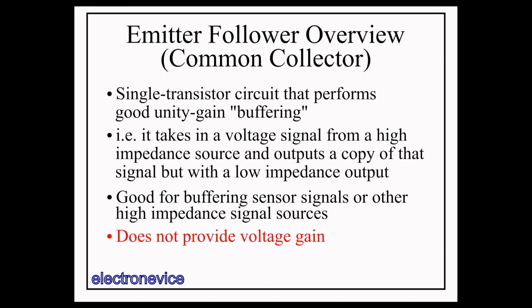It's important to note, however, that this circuit does not provide voltage gain. In fact, it provides a slight amount of voltage loss. But that is usually not a big problem, especially if there is gain elsewhere in the signal chain to compensate for the follower loss.